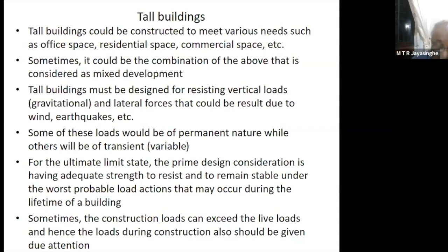Tricalcium silicate gives the strength after 14 days. Sorry, tricalcium silicate gives the strength from 1 day up to 14 days, and dicalcium silicate gives strength from 14 days onwards. So if you take a cement 50 years old, you will find those cements had 50% tricalcium silicate and 25% dicalcium silicate.